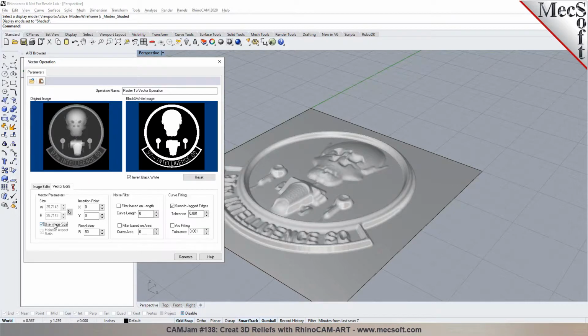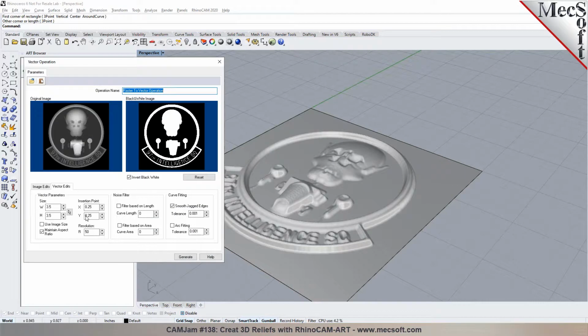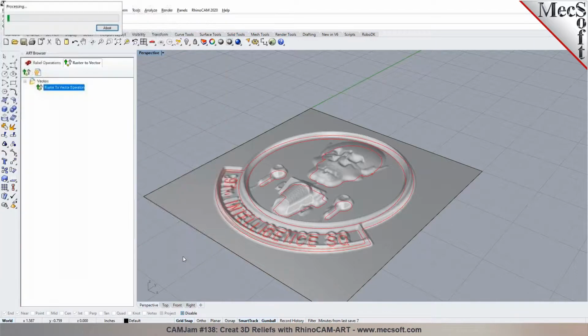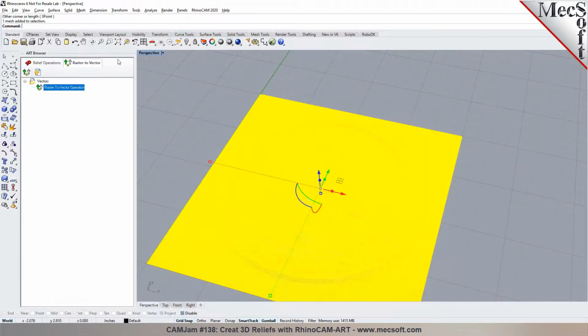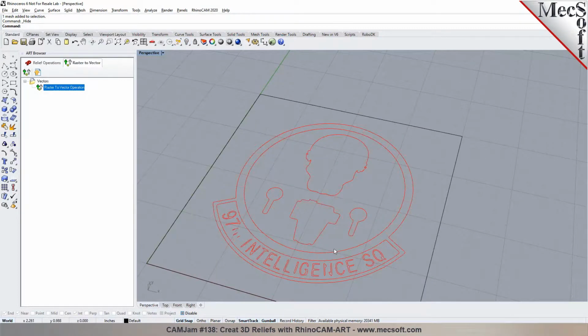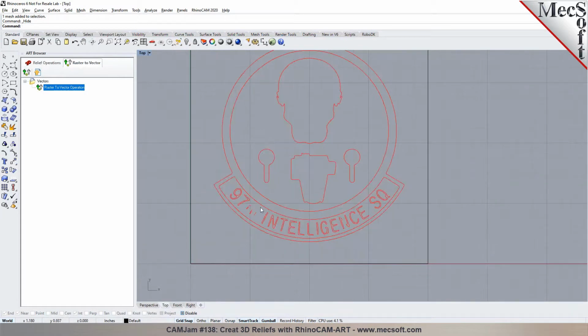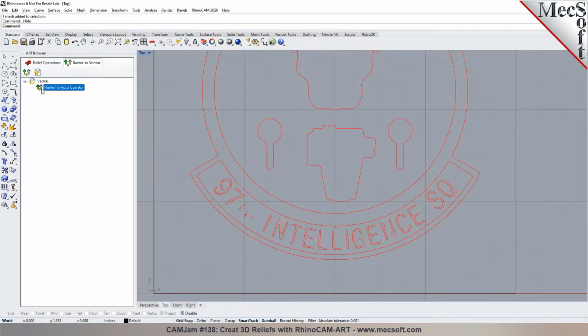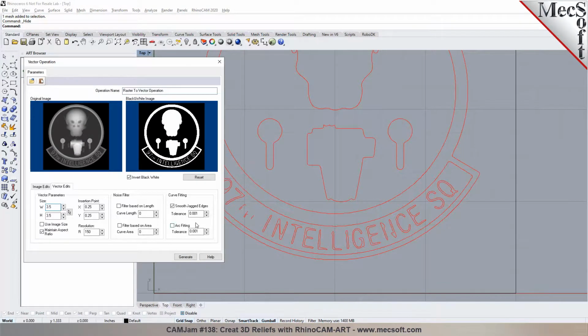And then I can go to vector edits. I can specify a size for it. Again, I can snap to these 2 points right here. And then I can set a resolution. And then pick generate. So in this process, it's going to create those curves. Let me hide this in here so it's easier to see. So that was a raster to vector operation I did by using those curves, right? So based on what's visible in here, it creates them, and you can also adjust the smoothness.